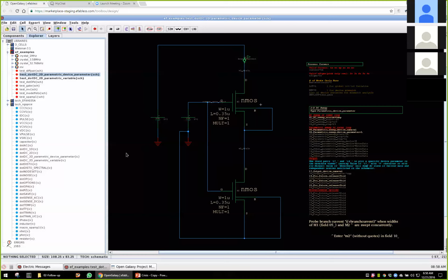For example, sometimes in Cadence you use something like cross and tell me what's the x value. I may make a function using Perl script to help me find the y value at an x value, or this can help in the gm over ID if I'm going to design using the gm over ID method.